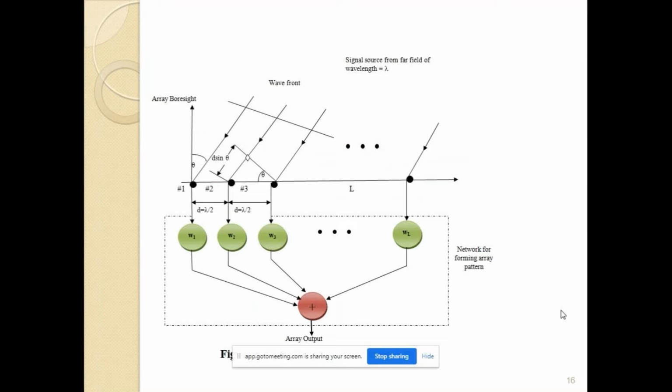Now, when we see the signal model, this is very important for beginners. It will be very helpful to understand how the diagram is drawn and how we can develop a mathematical model of any smart antenna system. In smart antenna systems and the array signal processing concept, the antennas are phased array antennas or MIMO antennas, and how we use them and how we make the alignment is very important. When the alignment is shown on the horizontal, that is called a uniform linear array.